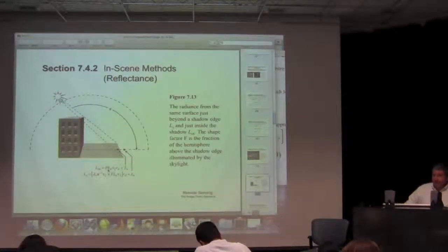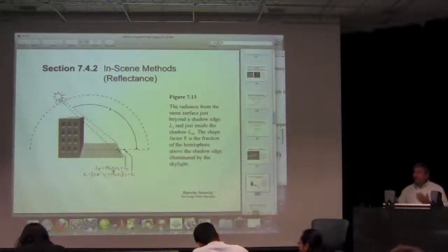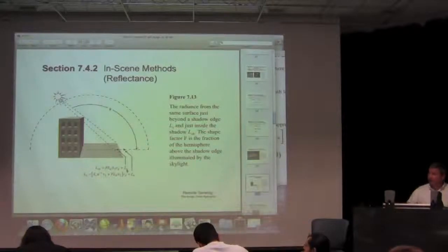Times the downwelling radiance, right, that you measured over the entire hemisphere, times the transmission through the atmosphere, times the reflectance of your target. Right? So you had your energy reaching the surface, LD. You modified that by how much of the hemisphere was actually sky. You reflected that off your target, RD, and then you multiply that by tau squared to propagate that energy up to the sensor. Right? Then you also add in LU, right? Because the path radiance makes up part of your signal.